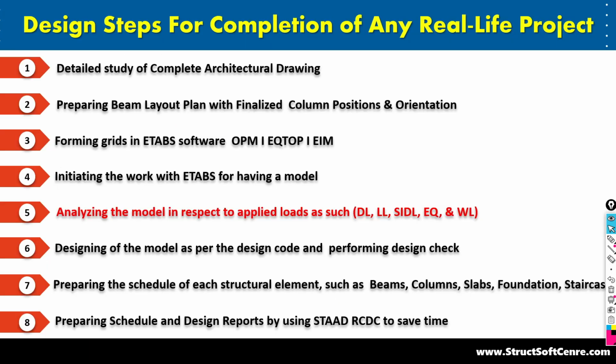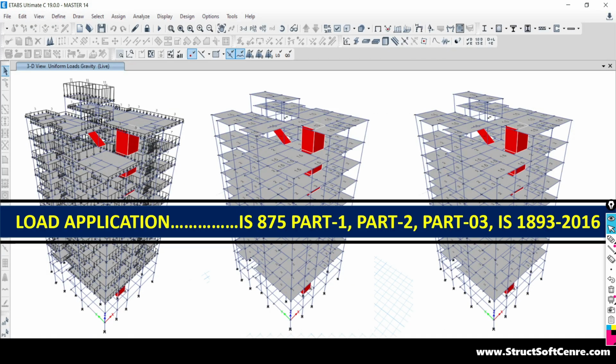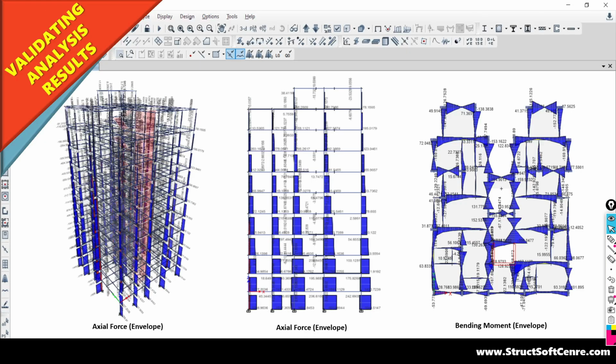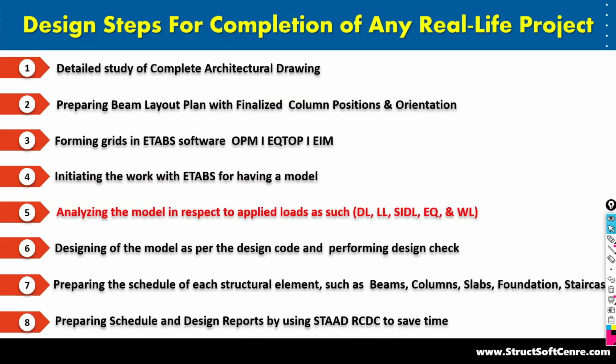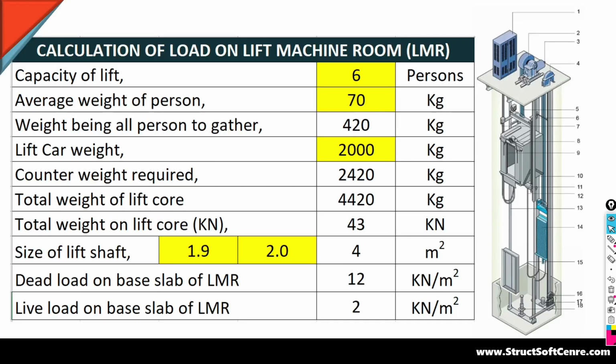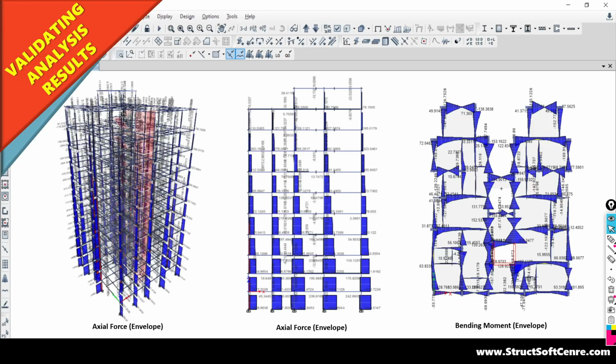You should have the skill to do the calculation, including how to do the temperature loading calculation. Everything you need to learn in detail. And with these calculations we have to assign the load over our structure: to beams, to slab, to column, and to staircase. Okay, after doing all of this assignment of the loads, we need to perform the analysis.